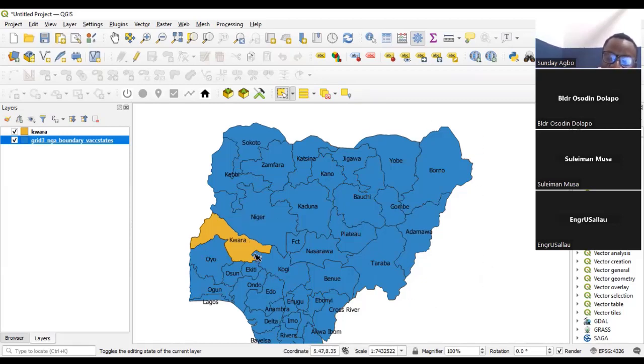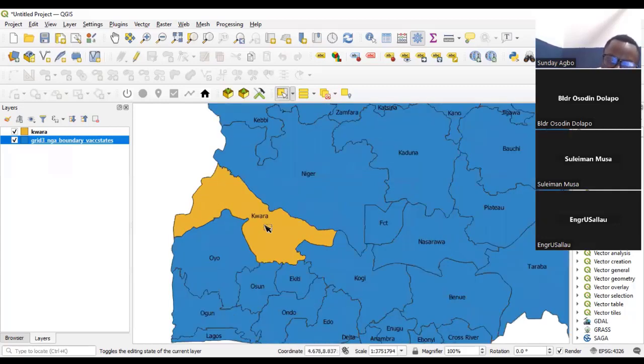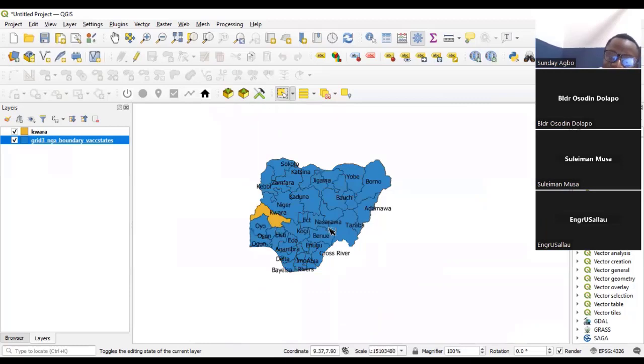And then within the Kwara State, now you can have the local government boundaries. Okay, if you remember from the grade 3, we have local government boundaries. We even have up to ward boundaries, right? So you can download that and then put them inside this Kwara State, and then actually indicate that local government that you want, or that project is located, and if possible the ward that the project is located. So if you produce those maps and send it to your client, you understand, they can now see how they can locate that property from where they are, you understand. So this is how you manipulate, or you actually work with your data.